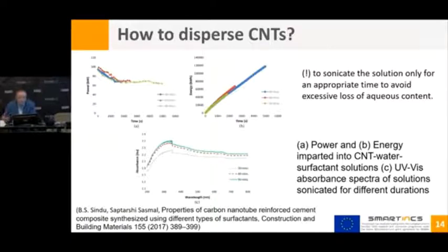But also there is the risk that nanotubes will be damaged, because of the cavitation field and because of the energy which is released into the solution. If we insist for hours and hours of sonication, there is the risk of breaking the carbon nanotubes. So this is something we have to avoid, and so there is a certain time during which the sonication has to be applied.